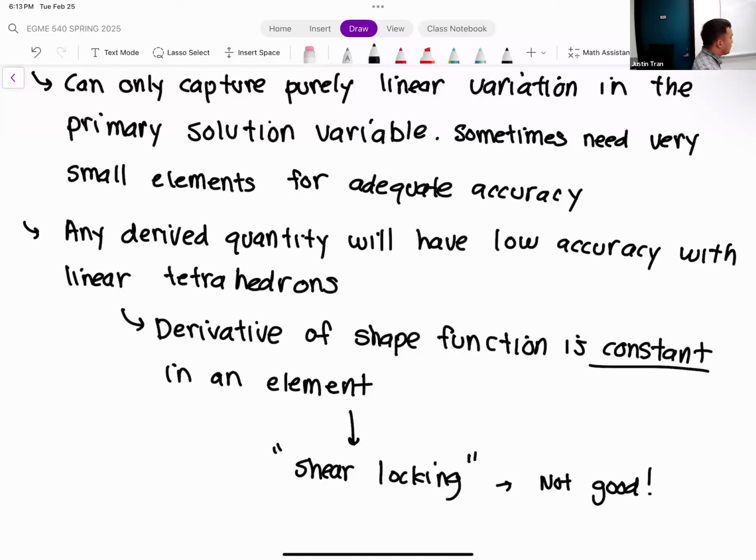So if you're just starting out, just learning ANSYS for the first time, I would say just avoid using linear elements. You don't want to even put yourself at risk of shear locking occurring, because sometimes it's hard to look at your results and say whether shear locking occurred or not. So for you guys, who are just learning ANSYS for the first time, I would say just use quadratic elements. It's much less of a risk there. You're going to incur some additional cost, maybe, but a lot of times it's good just to give you something.